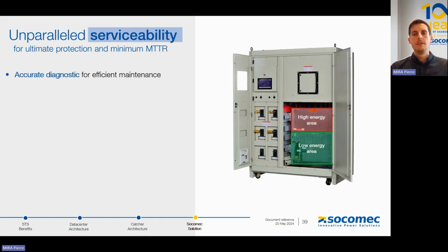High level of serviceability in the Socomec static transfer switch is thanks to the module design. So having this power module static transfer switch will help to isolate all of the boards. So here we have an example of a static transfer system powered by a Socomec static transfer switch module. So when we are on bypass in the static transfer switch system, we can access the Socomec power module at any time, having this power module isolated completely from any voltage.